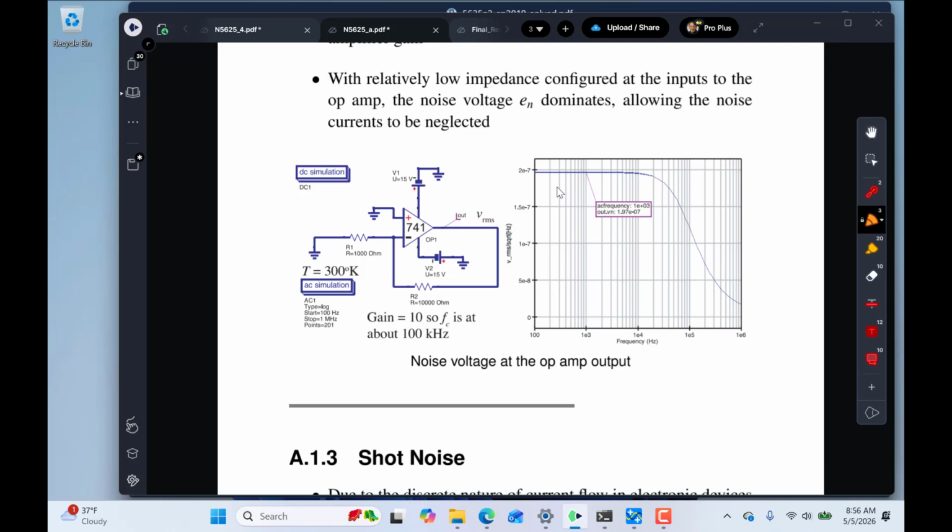But it turns out one of the capacitors used in the loop filter design itself, this was an analog loop filter, had been treated with a chemical to clean the solder flux on the PCB, and that solder flux cleaner got inside the chip capacitor and messed it up. So now it became a very noisy electronic component. How did we figure that out? We took the capacitor off and put a new one back on the board, did not clean the board, and the problem went away.